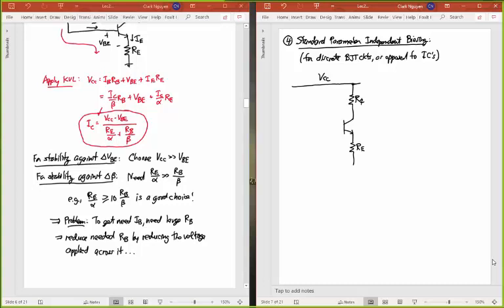So it has that collector resistor, it has that emitter resistor, but now instead of just having a base resistor going straight into the base, it uses a voltage divider of resistors. And I'll call this one R1. I'll call that R2, and I could say that I have a bias current, I bias, which I'm sort of drawing through that whole thing. Maybe I shouldn't draw it through the whole thing. Usually I'll draw it through the whole thing because the base current should be much less than this current, but I'll just do this right now. That's now our I bias current running through this.